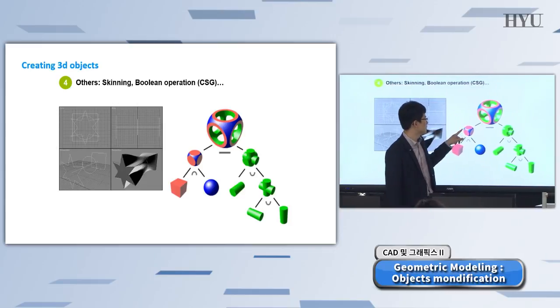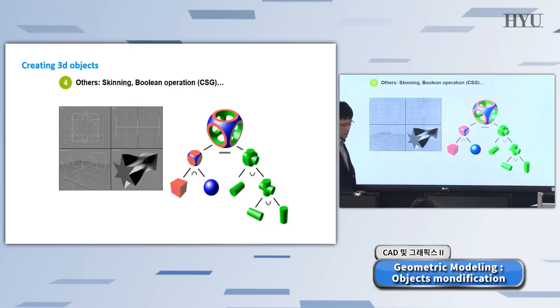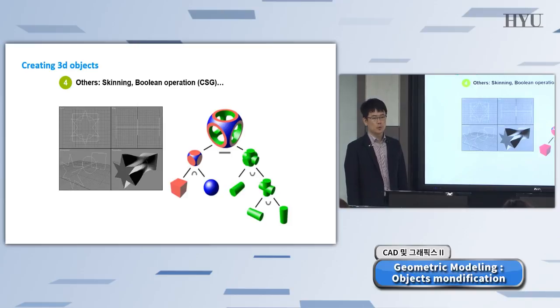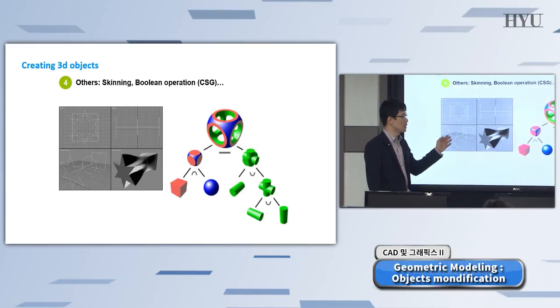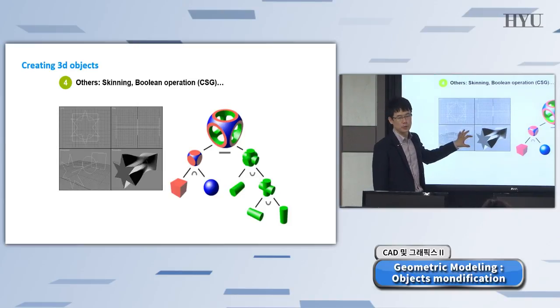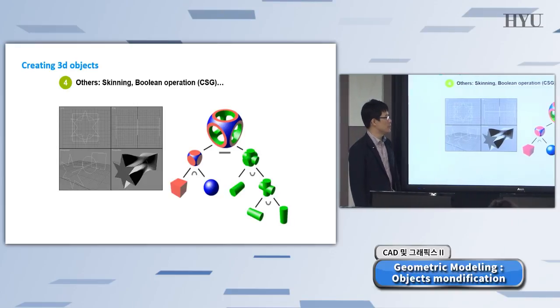And then this object minus this one. That's the final product, okay? In solid geometry, that kind of operation is common and usually happens without any problem. But in a surface-based model, there is Boolean operation, but it's error-prone, with lots of errors, simply because it's surface-based 3D calculation. It's not that easy.